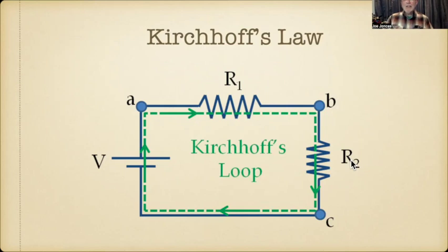What's the current across R1? Did I say current? I meant voltage. Correct. So what is the voltage if you've got your negative lead here? What's the voltage right at this point here? 2.5 volts.